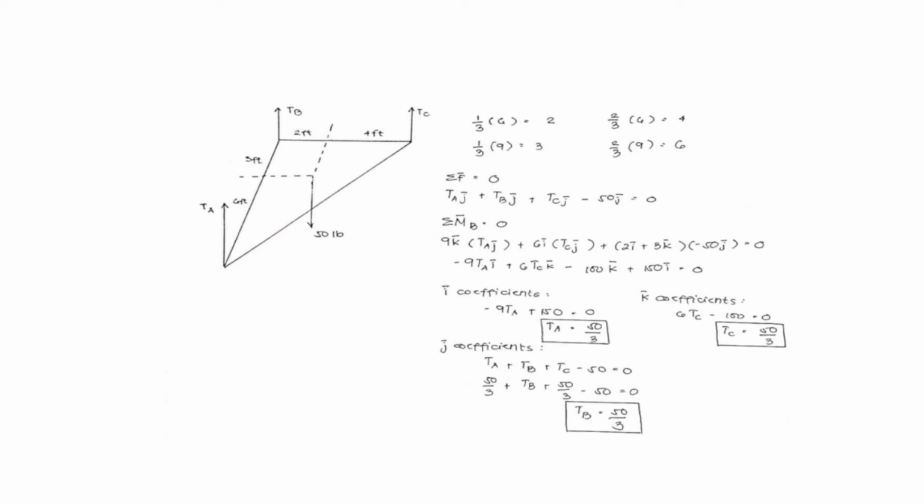First, we multiply 1/3 by the measurement of the triangle on both sides, which are 6 and 9. And then we multiply 2/3 again by the dimensions of the two sides of the triangle. So we must always state that the summation of all forces is 0. Then we'll get the equation of this. And as well, the summation of moments must be equal to 0. Then we'll arrive at this equation and then substitute the values.